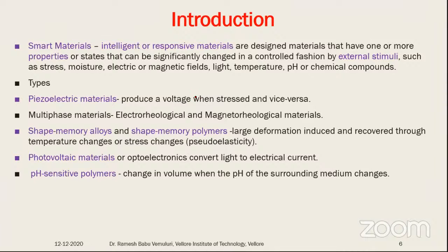They are responsive materials, designed so that one or more properties or their state can be changed by some external stimuli, sometimes even without any external stimuli. So what are the various characteristics? Let's say we talk from the vibration perspective: natural frequencies, mode shapes and damping characteristics. Once they change their state automatically, obviously there is a lot of change in their vibration characteristics.